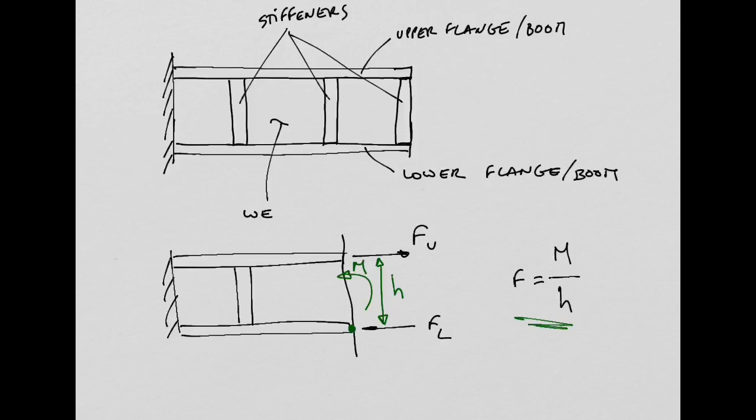So you can obtain the forces in the flanges from the bending moment that you learned in year 1. Remember when we did bending moment diagrams? Divided by the height of this web, okay? So these flanges will carry this kind of axial or longitudinal loads.